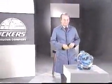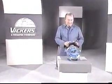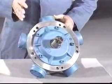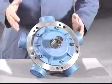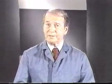Last but not least, we have the radial piston motor. Radial motors, while not as common as those previously mentioned, are found in applications where low speed and high torque are needed. This type, which is often used in applications such as an injection molding machine, has a maximum speed rating of 100 RPM and a maximum torque rating of up to 16,000 pound-feet. The capabilities of this type of motor often eliminate the need for a gearbox.